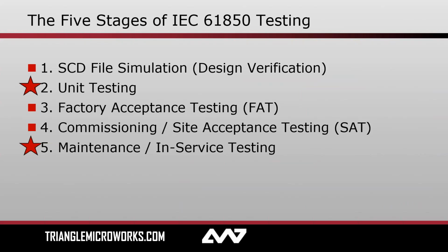In the factory acceptance testing phase, or FAT, I typically have maybe one bay or a group of devices that work together to perform some coordinated protection, automation, and control functionality, but I often won't have all equipment together and connected via a network at the same time. In that scenario, I might need to simulate devices from other bays in order to test inter-bay functionality.